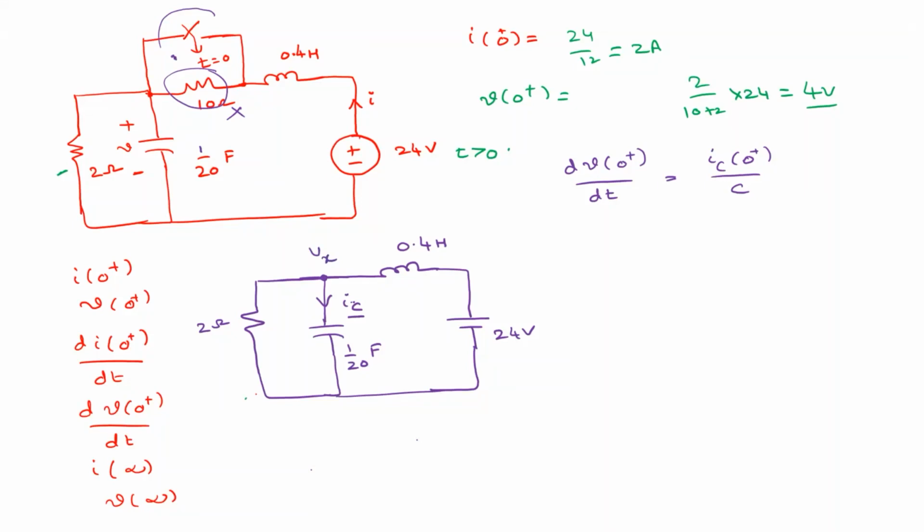Which one? No, tell me. Which is the suitable thing? Sir, loop method. Which loop method? Sir, we need to calculate KVL, because with the node voltage method we can't do it, as we'll have no relation for IC. Okay, yeah. What is the other method you can use? Loop current method, sir. In which one will you apply loops? Sir, in both.